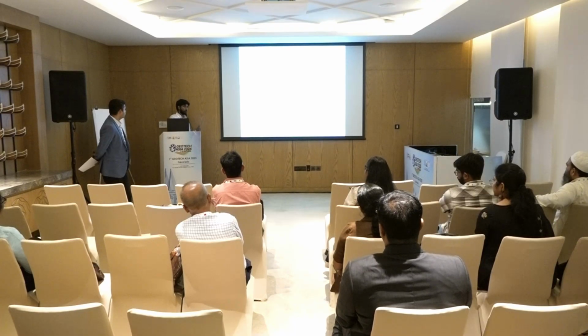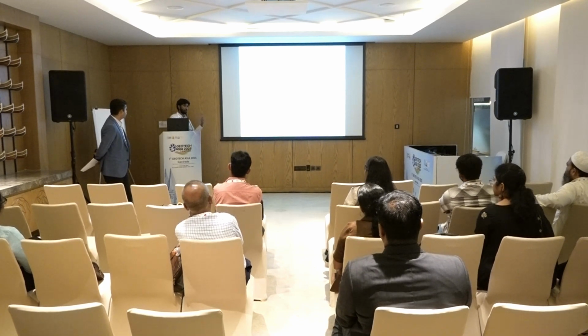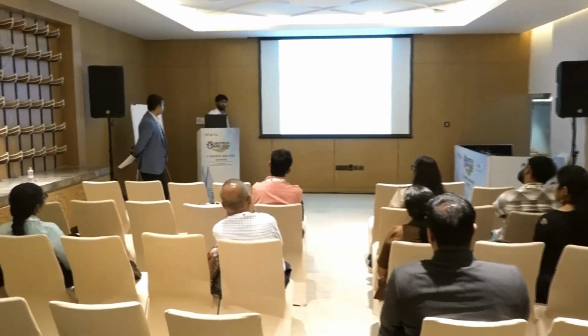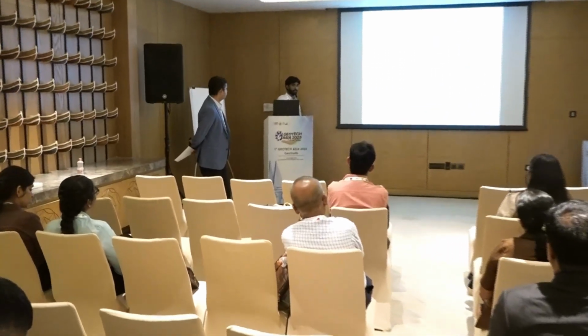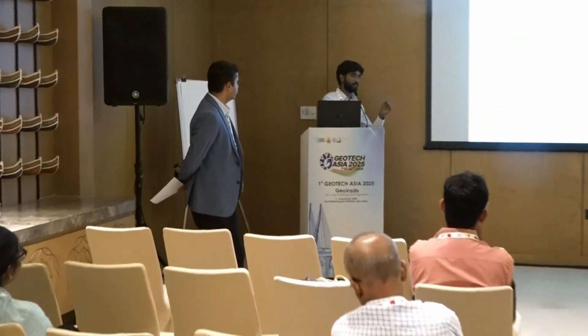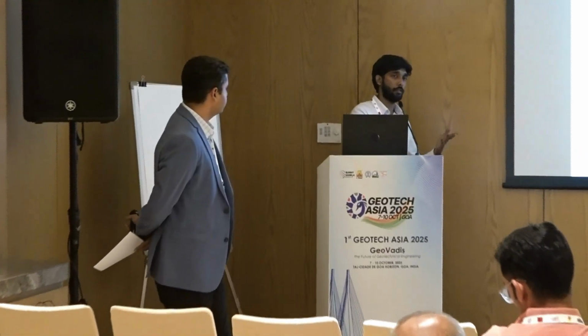If I go beyond 500, I cannot justify the higher temperature, which cannot be an economical way to produce the biochar. Even at 800 or 900 degrees Celsius, we get more carbon content, but as per the literature, getting more than 50% carbon is sufficient.